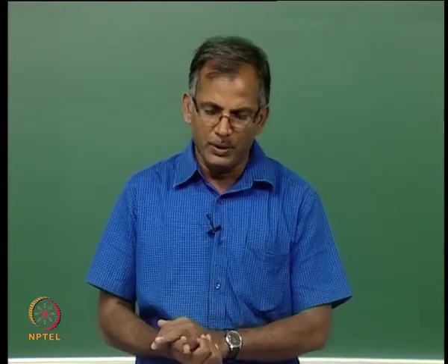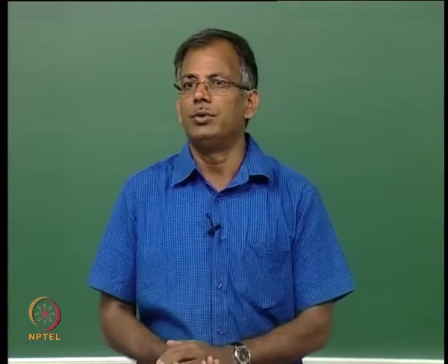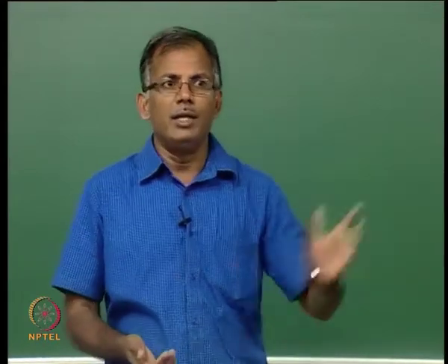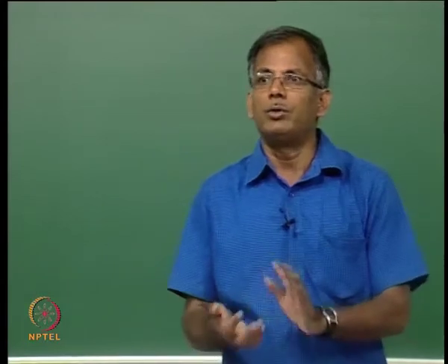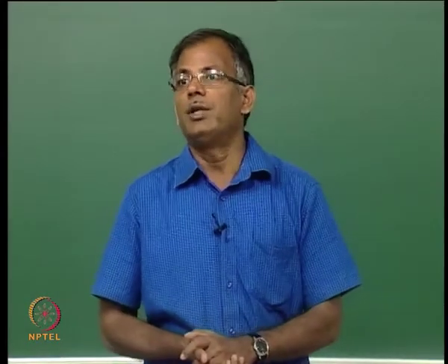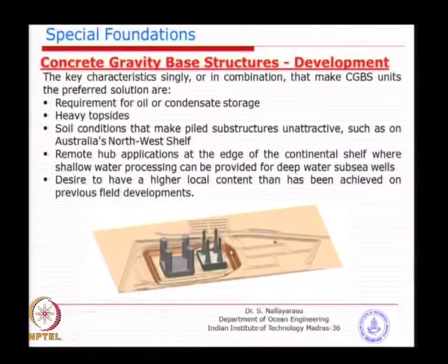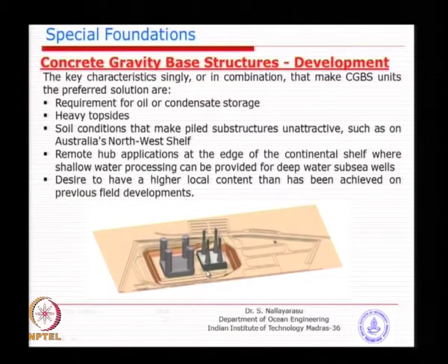One of the simplest ways is to float out. That means you require a dry dock wherein you construct this in a dry condition and then flood the dock, and it gets buoyancy sufficient enough to float itself. You can either tow only the substructure or tow it together with the superstructure placed on it, depending on the design conditions. That means the primary design requirement will be buoyancy.